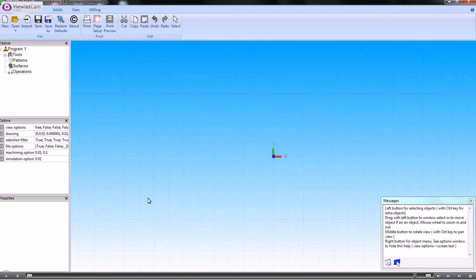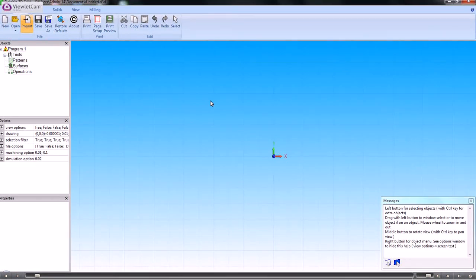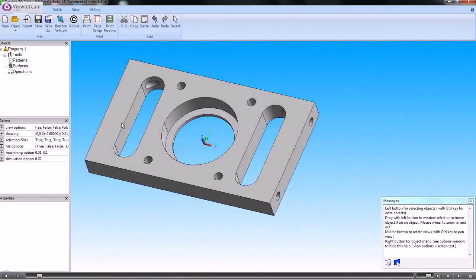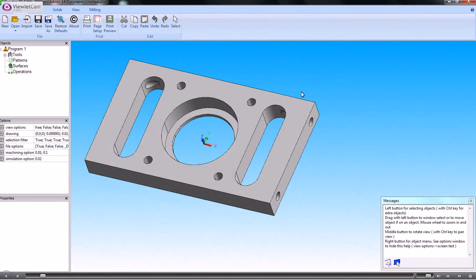In this video we'll show you how we can use Dolphin 3D CAM to import an IGES file and machine some 2D shapes. So this is the 3D system, so let's import our IGES file. So that is the file that's been imported. A couple of things we need to do first of all is to set up the part and the datum.